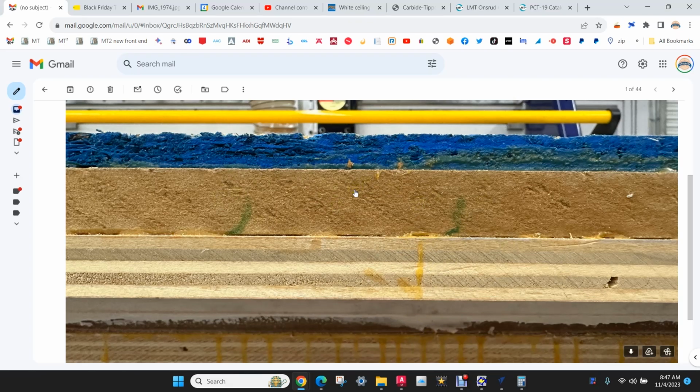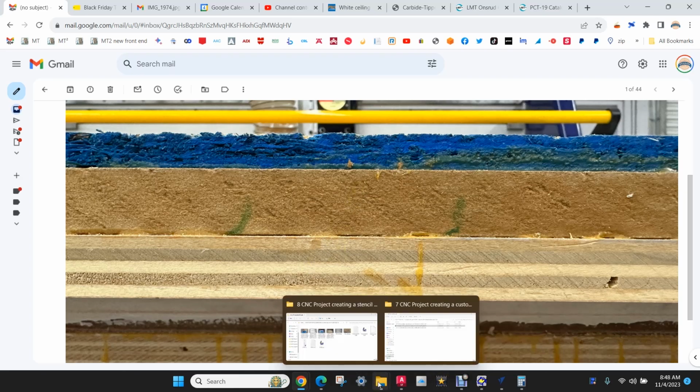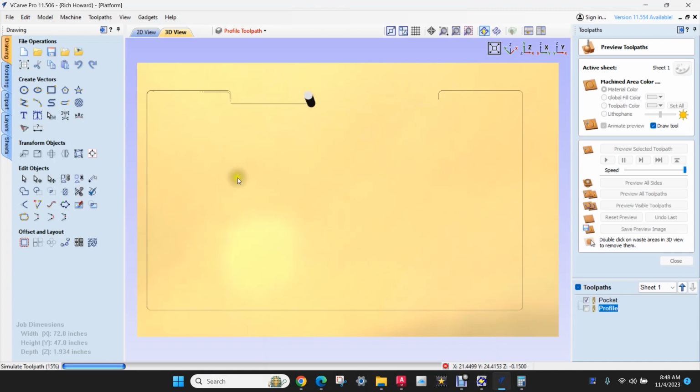So hold down. I'm going to pocket without holding down because the material is so epically heavy. I'm also going to turn on the vacuum. I don't think I'll have much holding it down, but I don't think the workpiece is going to move. But when we get the pocket done, I'm absolutely going to fasten through the pocketed area, which we're creating now in our toolpath. I'll throw some hold down in the center here.